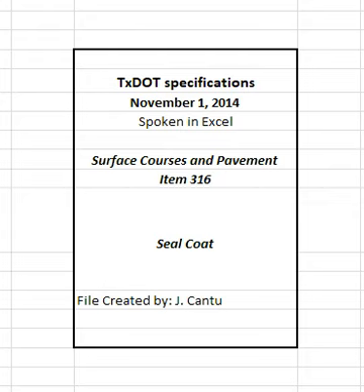4.2 Temporary aggregate stockpiles. The engineer will approve the location of temporary aggregate stockpiles on the right-of-way before delivery. Place stockpiles in a manner that will not obstruct traffic or sight distance, interfere with the access from abutting property, or interfere with roadway drainage. Locate stockpiles a minimum of 30 feet from roadway when possible. Sign and barricade as shown on the plans.